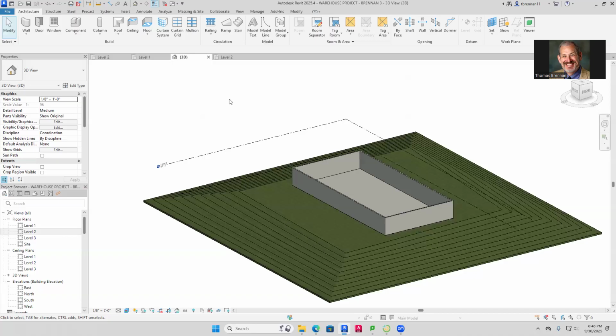Okay, now here we go. Now here's the deal. I mentioned there's a roster over there. We did the first item and the second item and the third item, and the fourth and the fifth. We did all those. So we created topography for specs given in class. I gave you those specs and you did that. We modeled a rectangular warehouse with the following parameters. The second floor wall is generic 8 inches. Top constraint was level 3. We did that. Warehouse is 100 feet by 50 feet.